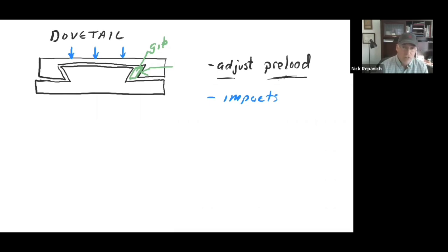Linear motion and motion control machines generally don't have huge variations in ambient temperature. The temperature comes from inefficiencies. So one of the things you're going to pay attention to, when we get to the drive mechanisms, is this ball screw, which is highly efficient, like 0.95. When you have an efficiency of 0.85 to 0.95, that means that 5 to 15% of the energy going into it is getting converted to heat, and the rest is used as mechanical energy.